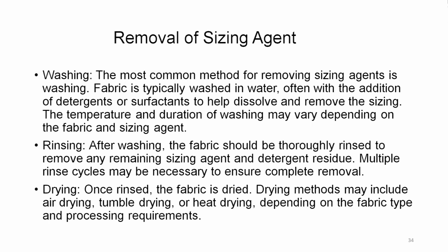So, we have seen that washing becomes very crucial. The most common method for removing the sizing agent is washing, whether we give it a cold wash or a hot wash. If we are giving a cold wash, a greater amount of water is required. If we are using hot water, then definitely it would involve lesser water consumption. So, the temperature and the duration of the washing will vary from size to size and from fabric type to type.